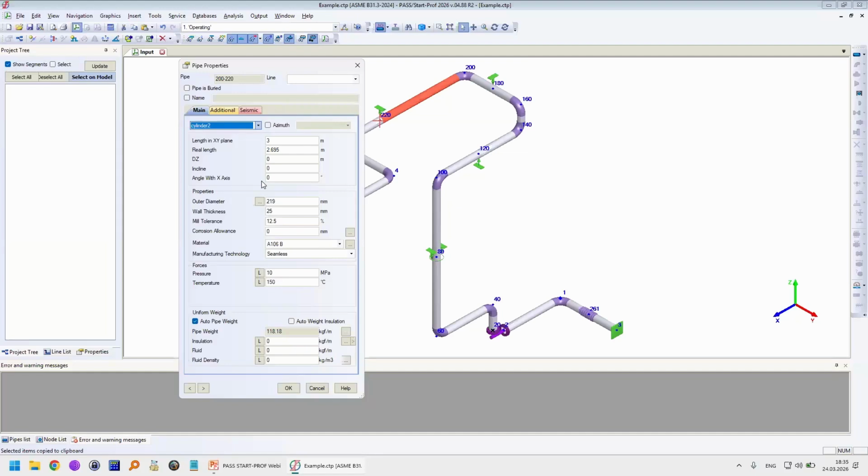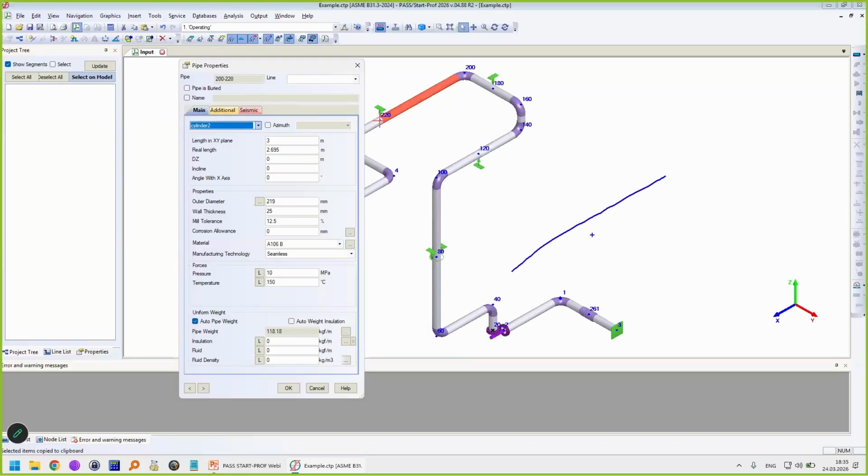If you like, you can investigate more, but I will just say that this system is very comfortable when you're working with long distance pipelines, cross-city pipelines, for example, the pipelines between cities, because you have the pipe, you have the plan profile, so you can define the incline or the slope angle. You can define the direction angle of the pipe from the x-axis or from the previous pipe. If you switch this option, the angle will be calculated from the previous pipe element.